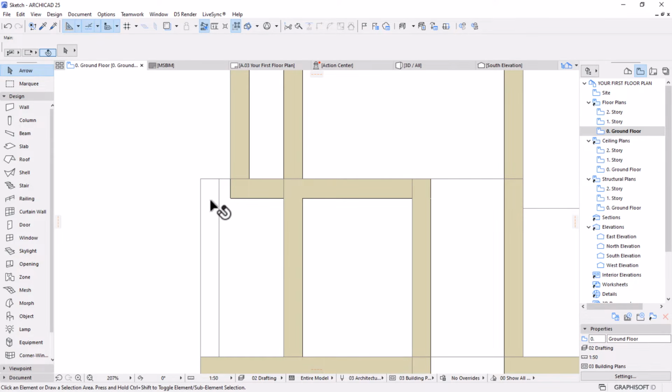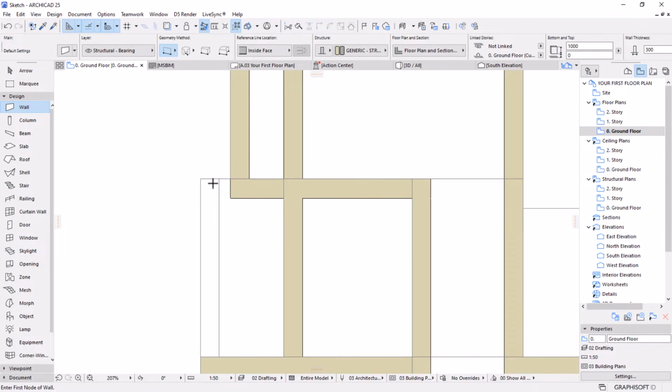So to pick parameter of this wall, I can go here and then say pick up parameter. The shortcut is Alt plus C. Let's pick up parameters here and then pick the wall. Let's draw this wall there. The location of the reference line is wrongly positioned. I'll just flip it like that, then place there.